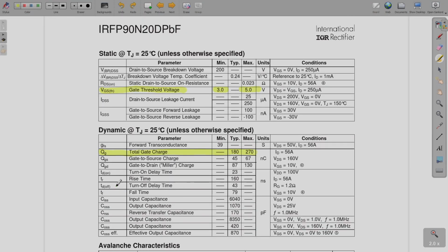Then further what we see here is that this rise time TR is also given. Now, this rise time, how you can use it, we just saw that equation that for this Miller time period we can write it as TR, which is equal to CRSS VDS off by whatever is the gate current IG dash PL.